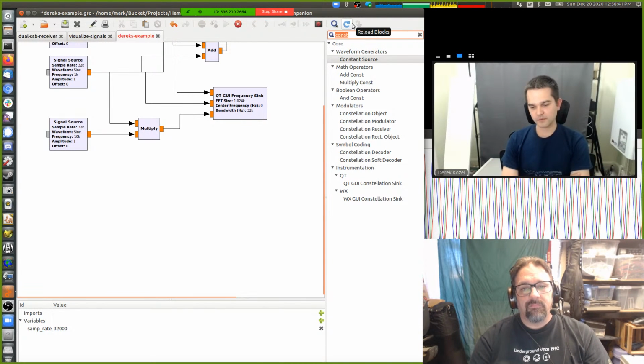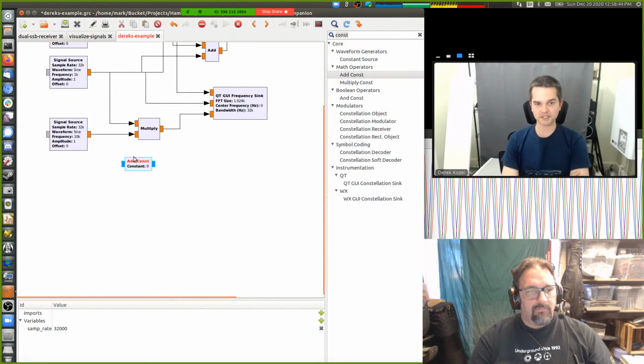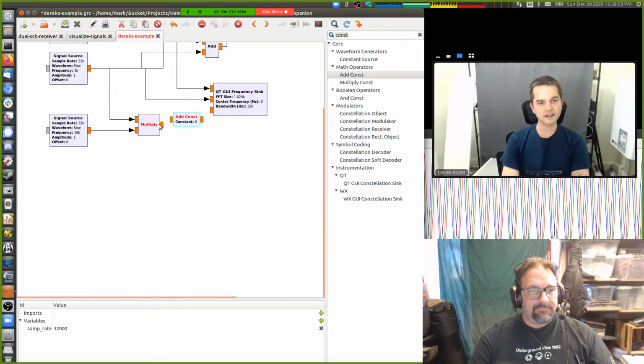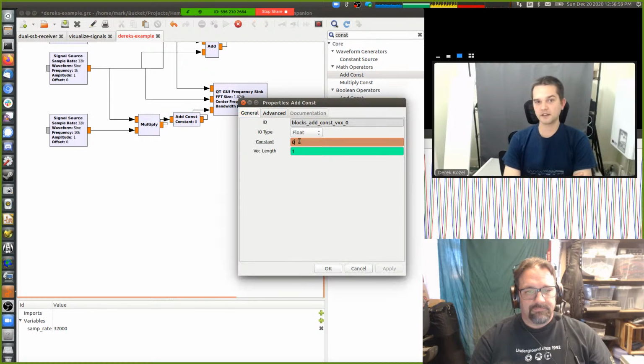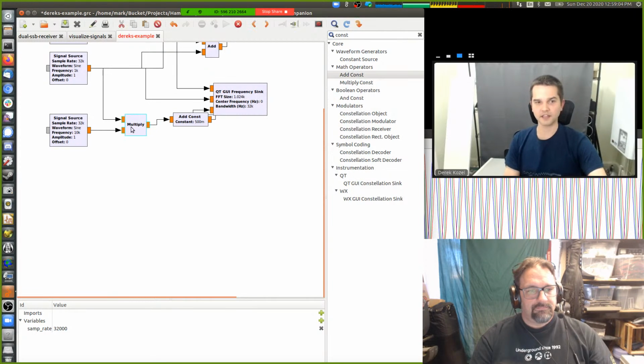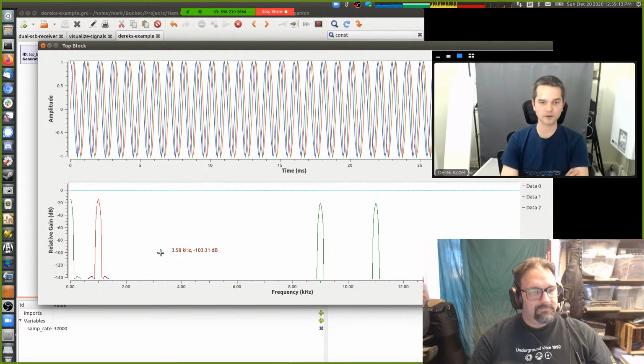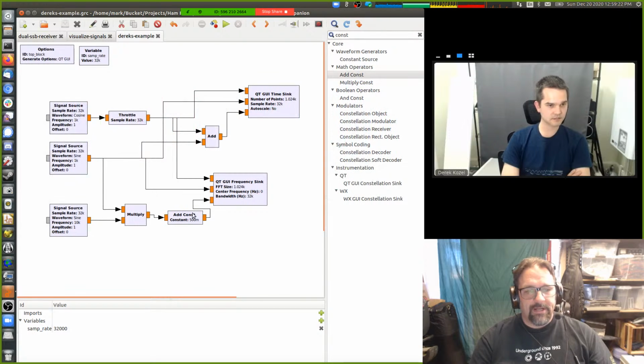So you get physical leakage across the mixer, where it's literally just the LO jumping between the pins and through the substrate. And then yes, any DC component will be a 0 hertz signal, where when you multiply it with the local oscillator, you'll end up with some of the local oscillator frequency, because 0 hertz times your local oscillator, or added with your local oscillator, will give you that. Oh, but that's giving it to me down here. You've probably added it in the wrong spot. You're right. I did. Yep.